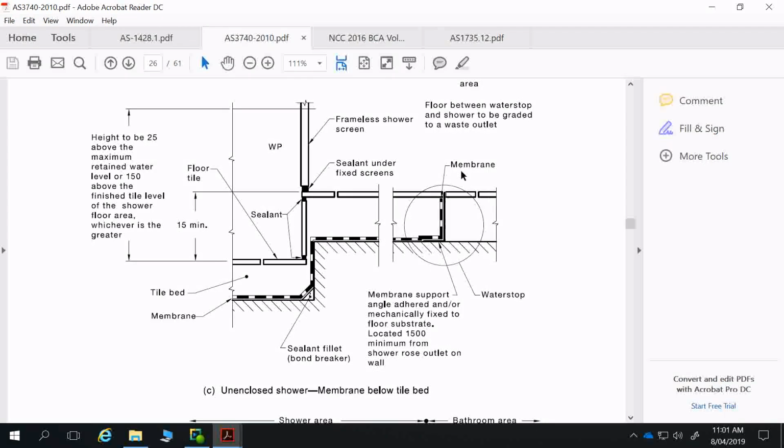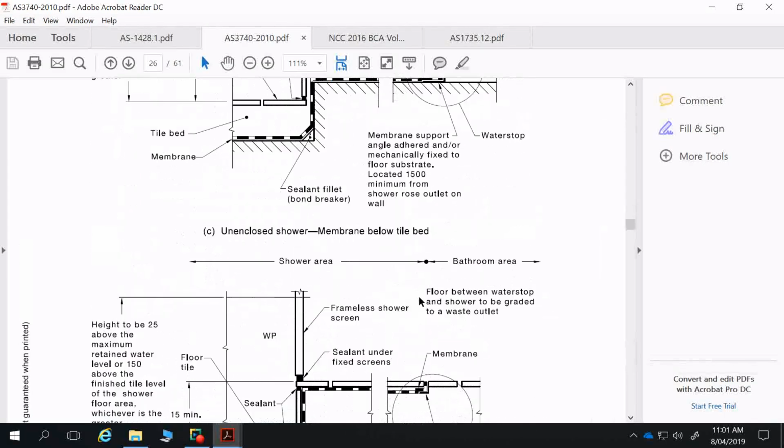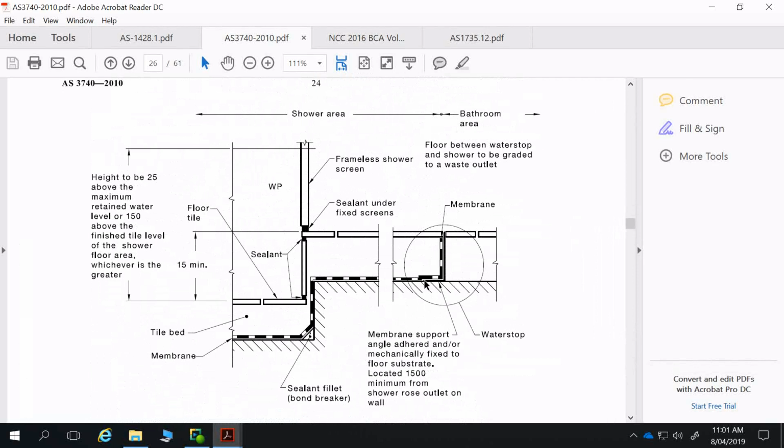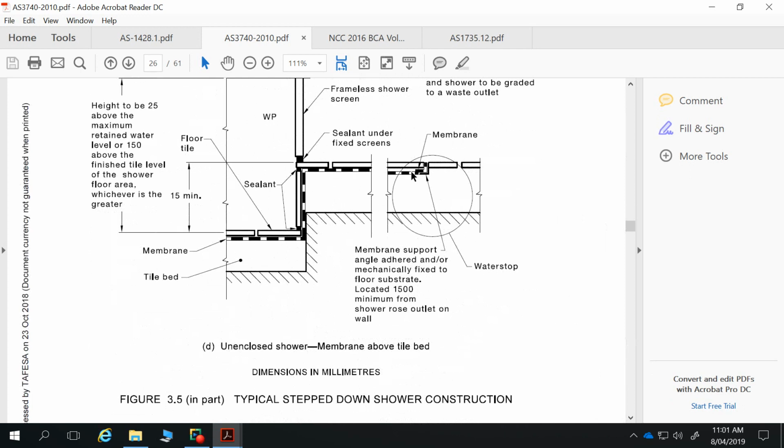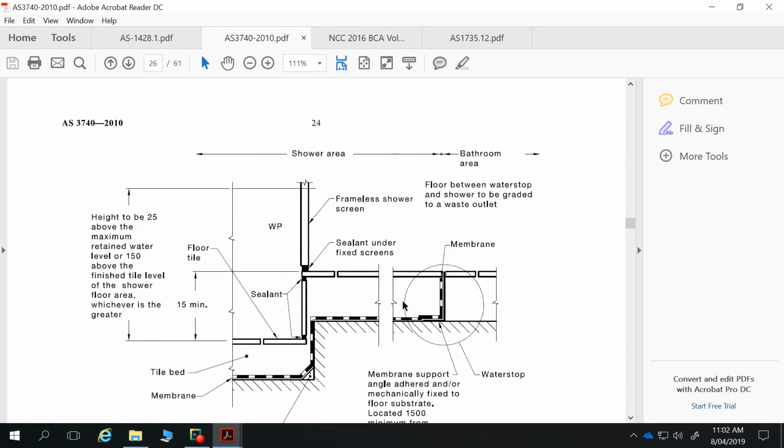But where we have, and there are two different approaches. This approach where we have a water stop going from our initial concrete slab all the way up and waterproofing underneath our screed. That's where we have a wet screed, and we use what's called a puddle flange to enable the bleeding of the water out of that screed. And then this is where we have a dry screed, where we have our waterproofing membrane underneath our tiles and a short water stop. This detail is by far the most common detail for use in South Australia.